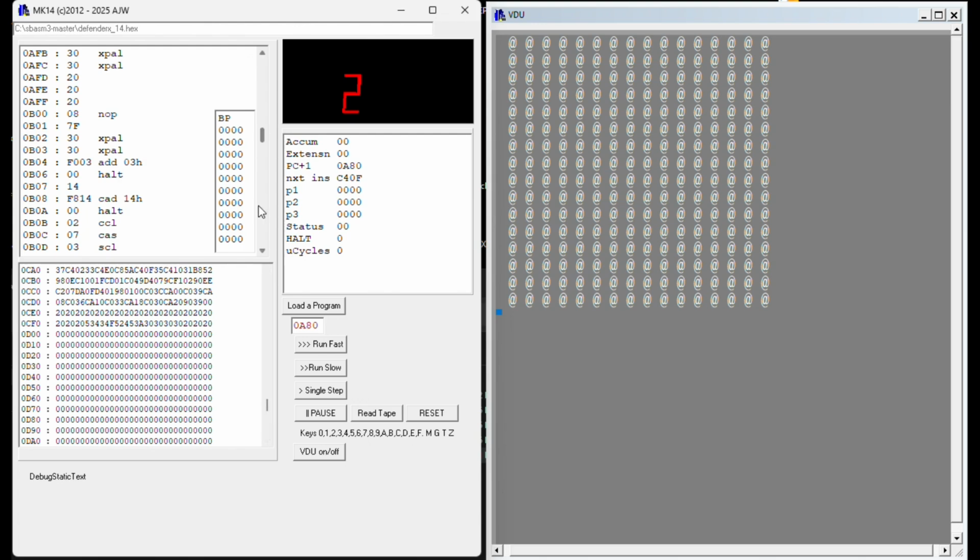The D space is for this 7-segment display, and that's not a mirror of the other spaces. E80 is another mirror. So that was 4 locations for the I/O RAM. So this little box displays that quite nicely. If the program itself that you'd written writes to one of those spaces, and then you refresh this space here, you will find that the mirrors do actually occur. So this is all taken into account in this PC application.